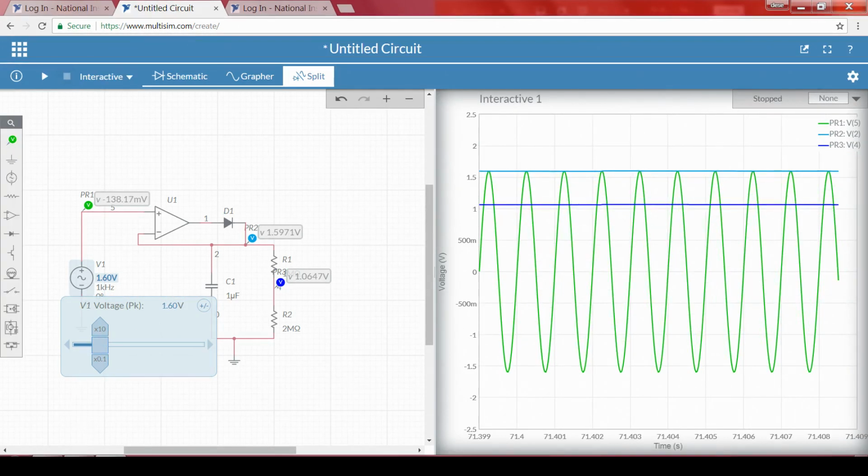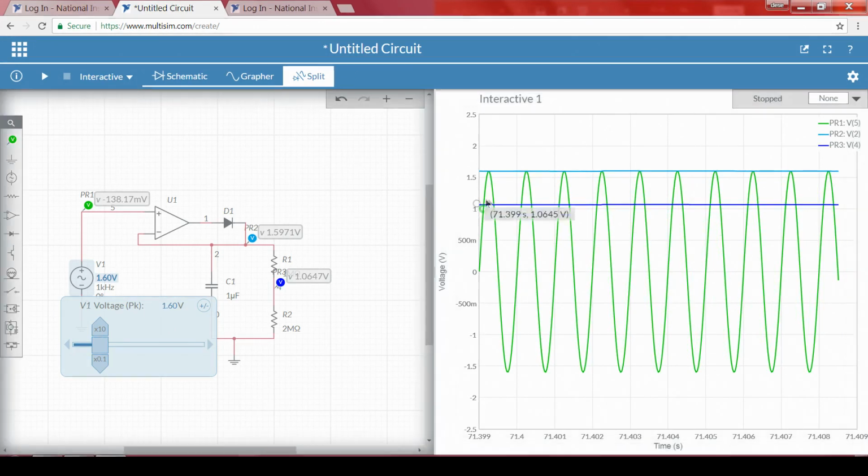Now, once we understand which input voltages are greater than this particular threshold, only those signals have to be passed. The input signal should be compared with this threshold value, and whenever the input value is greater than the threshold value, only that particular value has to be pumped out.